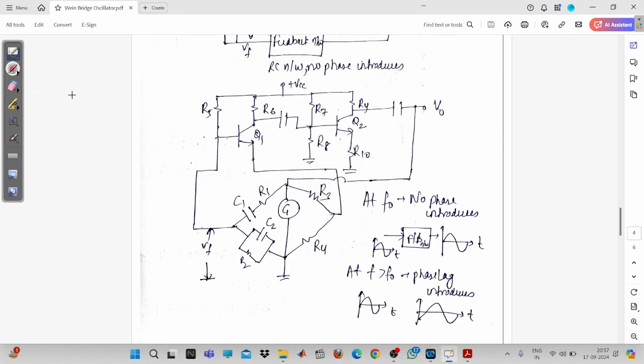This is a very simple circuit because you can see here this is the transistor. This is the Q1 transistor, and to the Q1 transistor we have connected this R6. Then to the upper one, this is plus VCC, fine. And you can see that the amplifiers are connected in cascade form. Similarly there are two transistors, because this is the first amplifier, this one is the second amplifier. So the output of the first amplifier will be connected to the input of the second amplifier, fine.